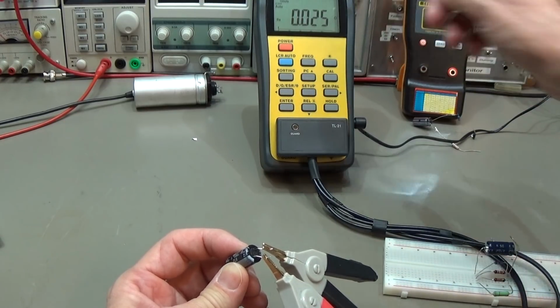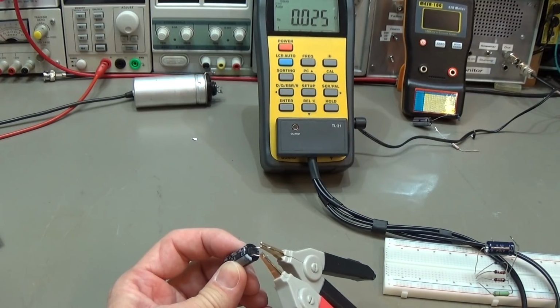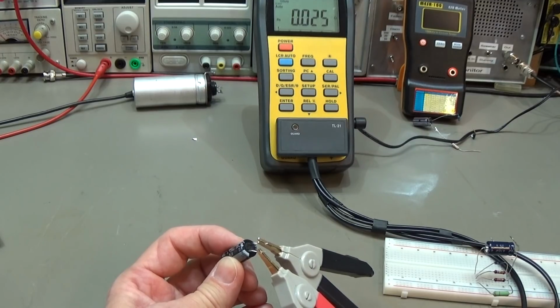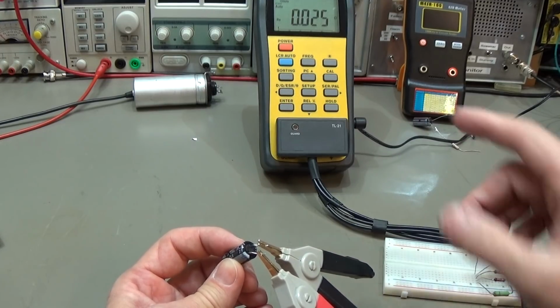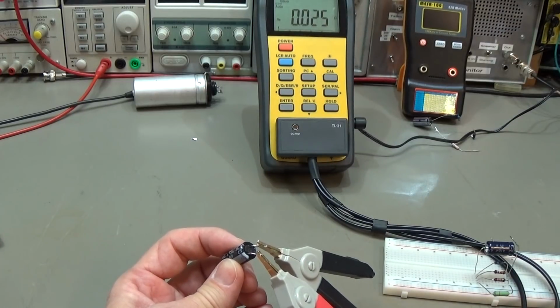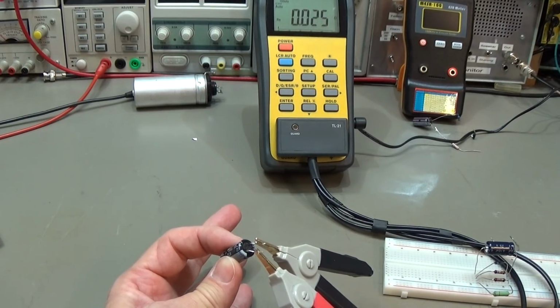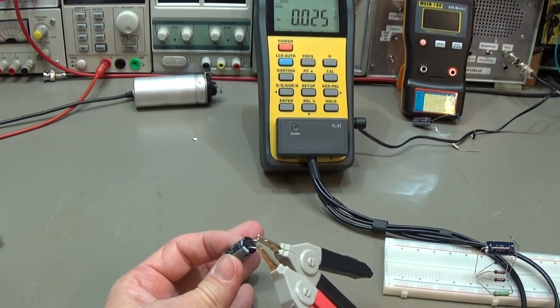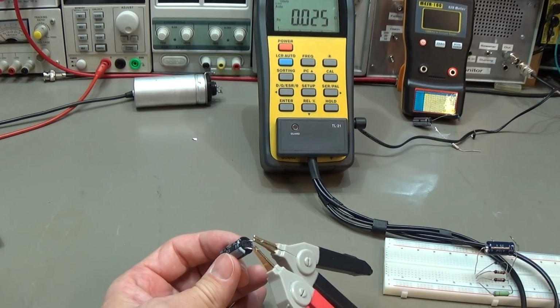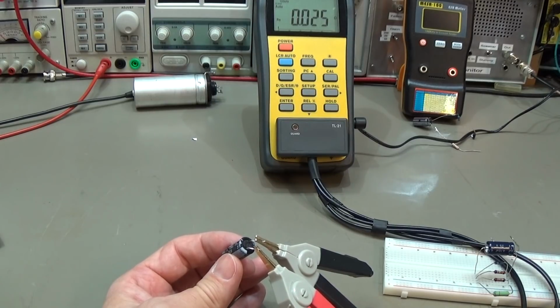It changed a little bit, so you see that we definitely have components in parallel which are influencing our reading a little bit, but more or less it is the same value. In circuit we already said this is a good and healthy capacitor, and now we can say the same. It is a good capacitor, and I guess you see that it is really possible to test in circuit.